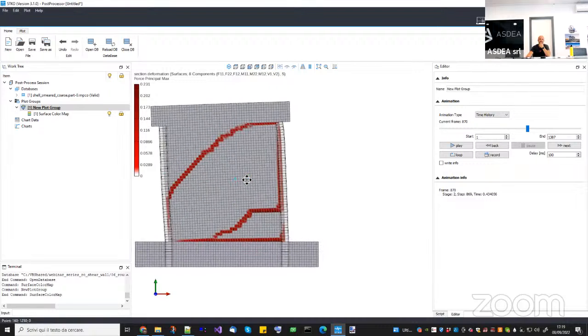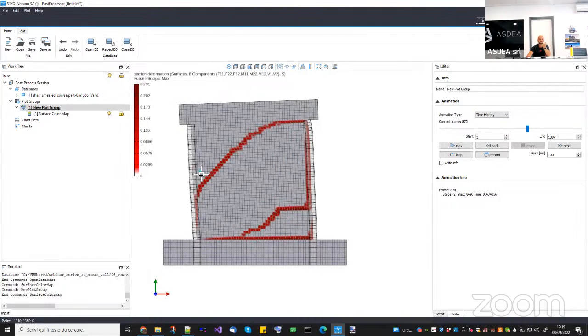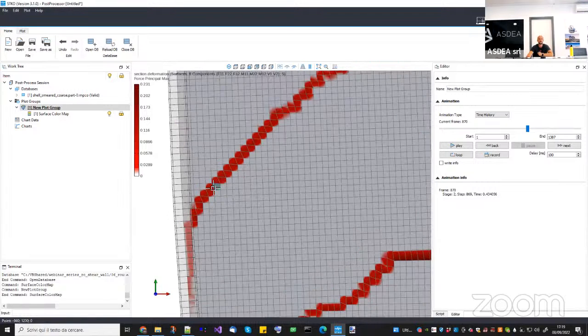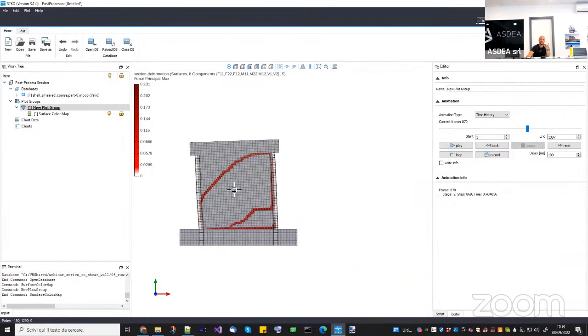But the wall can be as large as you want; the problem is that whenever you have a strain localization, the real size of the problem is no longer the structure itself. When the strain localizes inside a finite element, then this one becomes the size of your problem, and in this case it is smaller than the microstructure. So the problem is that you will never converge to an exact solution.